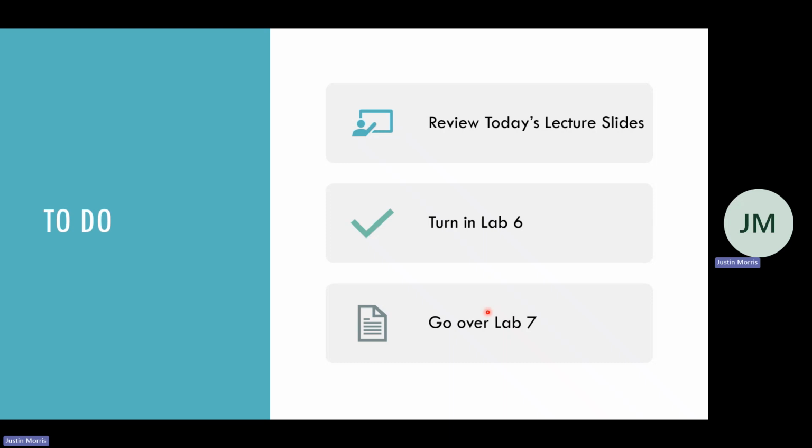Then I need to figure out which one had the least number of mismatches and output that, and then maybe write that result back to memory. So you have these different states: am I reading the class hypervectors, then reading the query, then comparing the query, which is the actual inference part, and then writing back the results. I have to repeat that, but I don't need to repeat reading the class hypervectors. I only have to do that once, but I do have to read the next query.